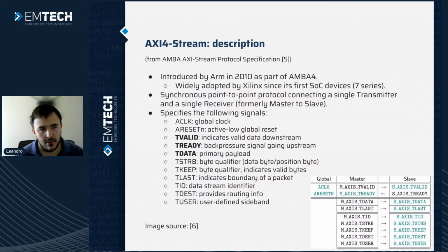So we can start talking about the specifics of AXI4-Stream. This was introduced by ARM in 2010 as part of the AMBA4 specification. If I'm not mistaken, I think it was commissioned by Xilinx, or so I heard. But what we do know is that it's been widely adopted by Xilinx since their first SoC devices, the 7 series Zynqs, and the transition to Vivado.